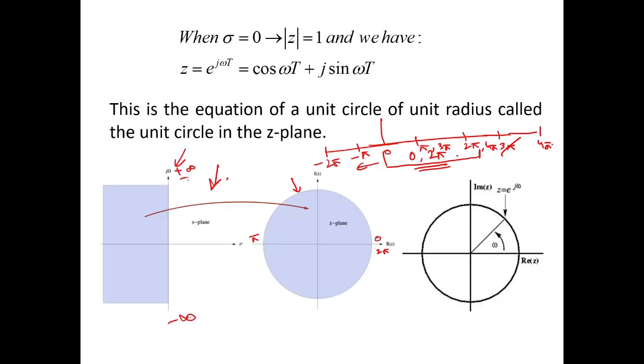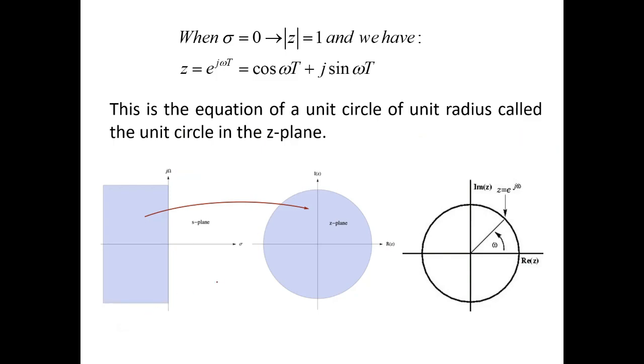Now coming over here again to the z plane, we have 0 and 2 pi. 2 pi is the maximum frequency. There is a criterion regarded as the Nyquist criterion, and the Nyquist criterion says the sampling frequency should be greater than or equal to 2 of fm, where fs equal to 2 of fm is the lower critical limit.